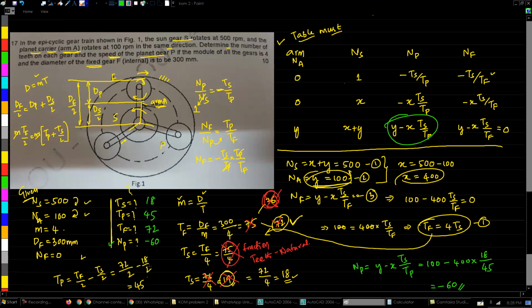Now some of you might say that the diameter was given to be 300 and based on that we got 75 teeth. And why didn't we go with 75 teeth? Fine. So is it correct? Are we allowed to make changes to the question itself? Well, to be fair, we cannot just decide the diameter of the gear first of all. Fine. So we'll just get some idea about what is the range of diameter, what is the approximate value of the diameter is what we can decide.